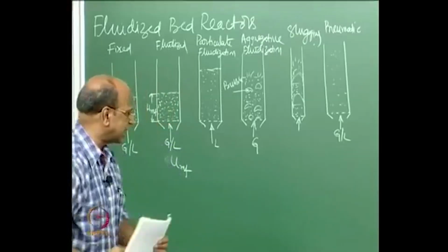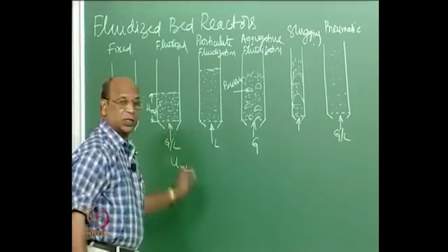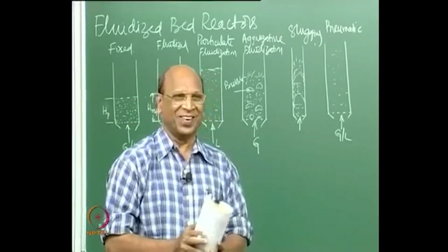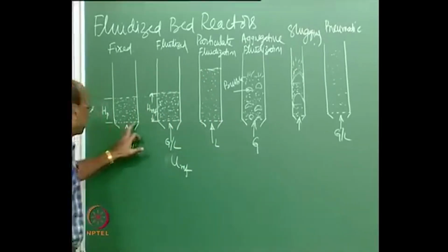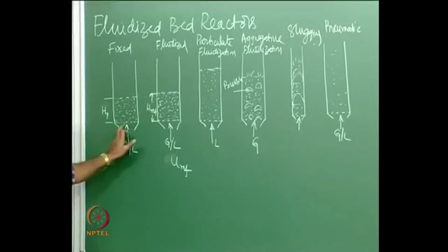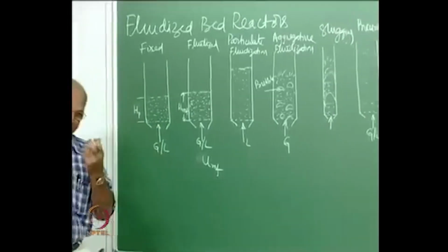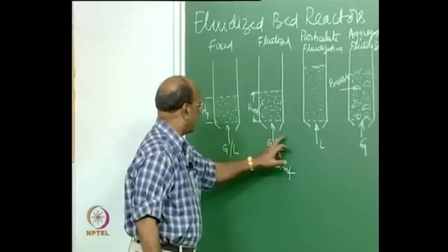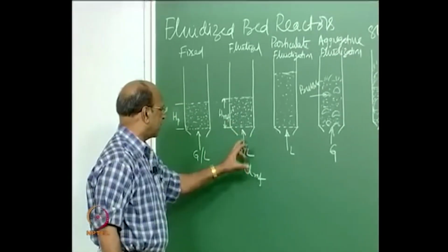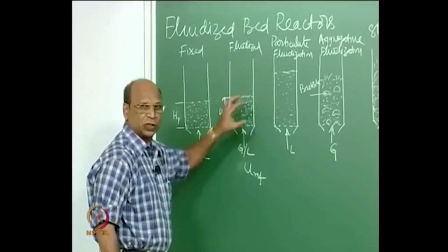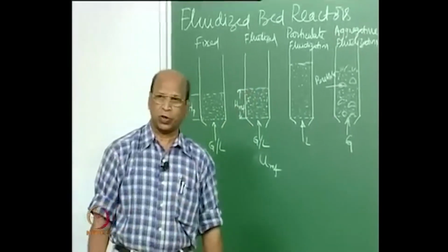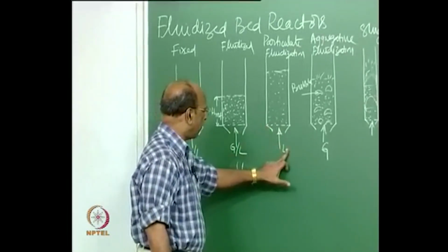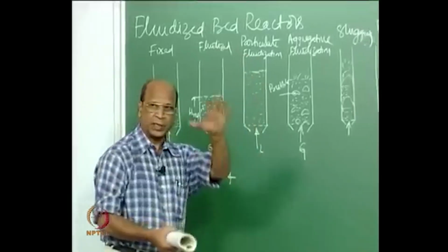So, what are the basic conditions here? Basic conditions for fluidization, first of all, it should be vertical. You should take a vertical column, okay, and then put a distributor plate, and then the distributor design also is one of the very important crucial factors, and then slowly increase the velocities such that the entire bed is supported by the drag force of the fluid, and beyond that if you increase, then if you have a liquid system, it nicely expands.